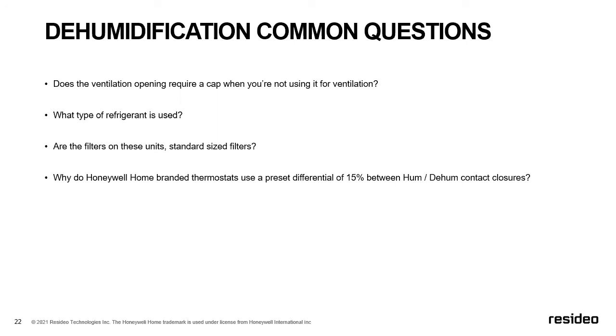If we wanted a flat line, for example, for a humidifier, for a cigar humidor, I'm not sure what the right word for that is, where they wanted to flatline at 50%, we had a humidifier and a dehumidifier both installed, but we needed to use two RedLINK sensors, one for humidification and one for dehumidification. So we have two external sensor points. Once we use those external sensors, we can say we want a flat line. And that's with the Prestige controller. We can flatline and drive both sequences.